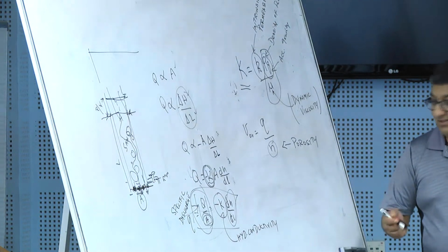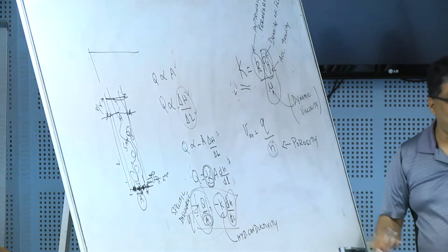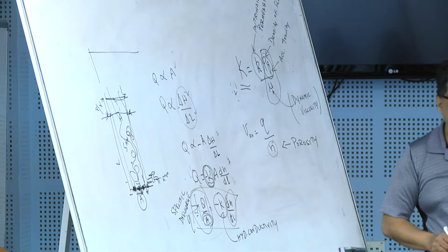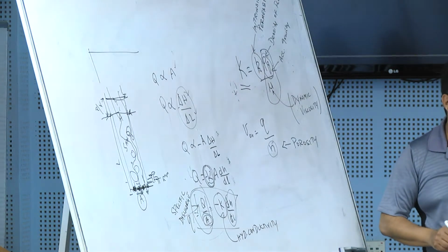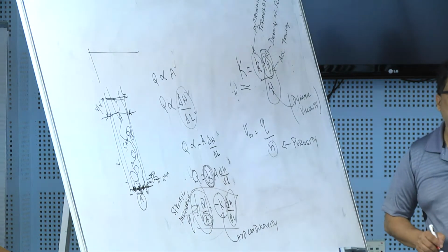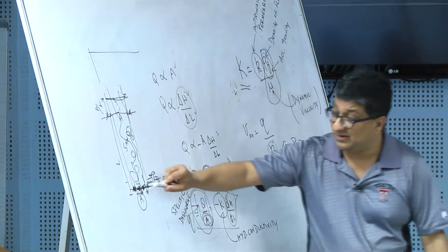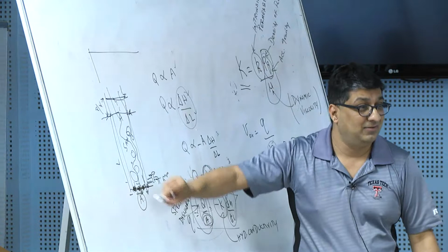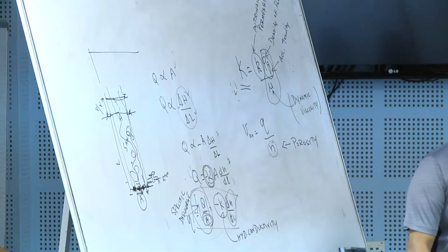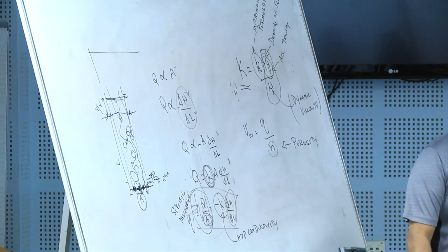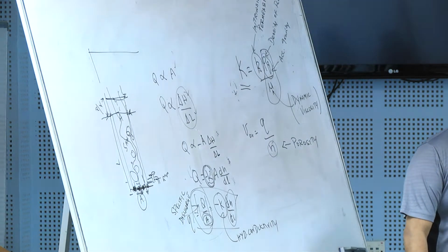As a result, Q is equal to velocity. But in groundwater, Q is not equal to velocity because when we do Q specific discharge, we average over the entire cross section, whereas the water is only moving through the pores. So if at all you want to talk about velocity, that velocity has to be just over the pores.